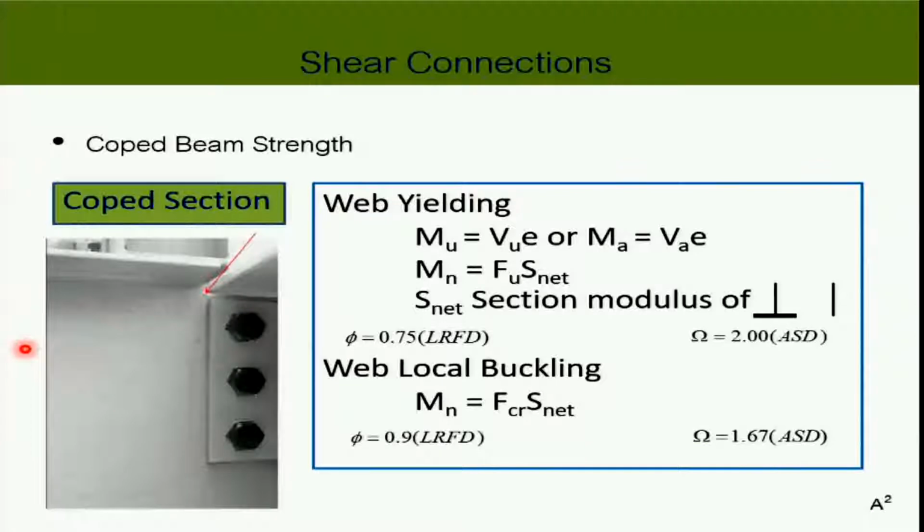And if that's the case, your beam may lose some strength here because the top flange is gone. And we may need to consider the moment capacity of this small portion to make sure that it can carry the force safely to the support, because we are losing quite a significant amount of section.